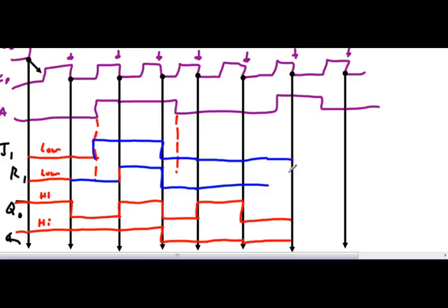I'm 0, 0, and the A gives me a 0. A is the one, it doesn't matter. I'm an AND gate, so I'm still going to be 0. I'm going to toggle. I'm going to hold because J and K are both 0. I'm going to toggle again, and I'm going to stay at 0. Now, is that what they say? Oh, look at that. Totally awesome.